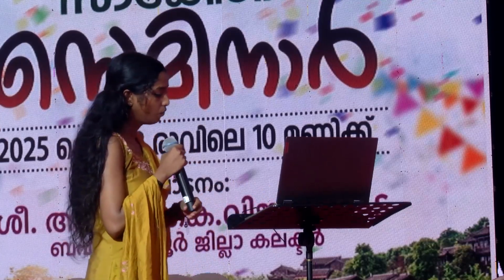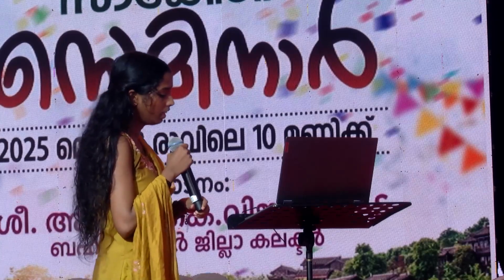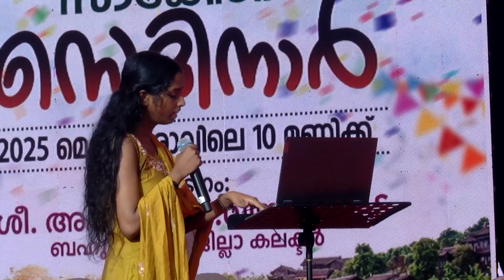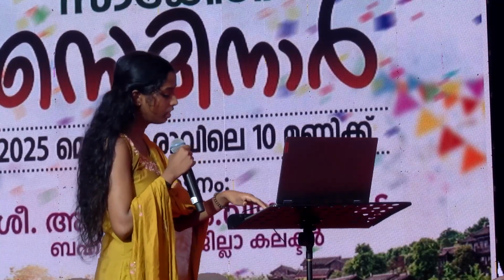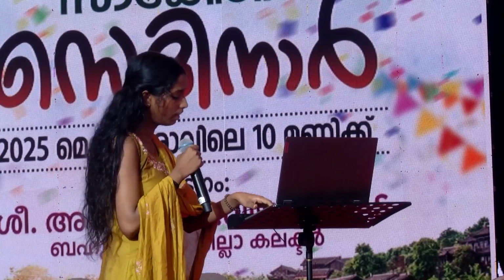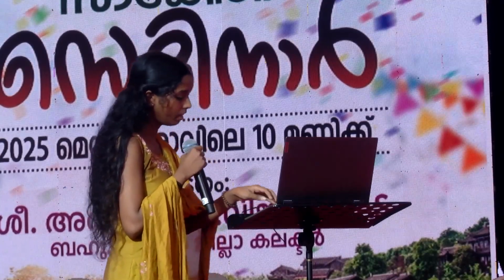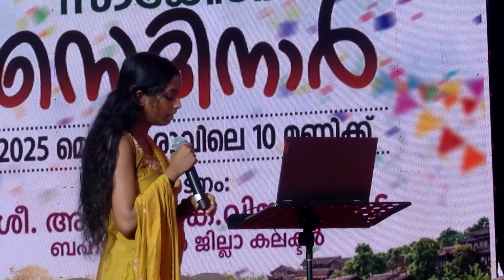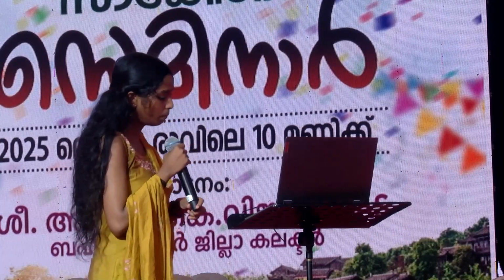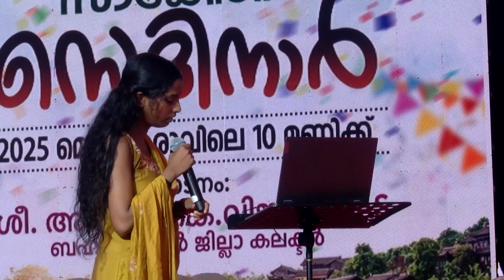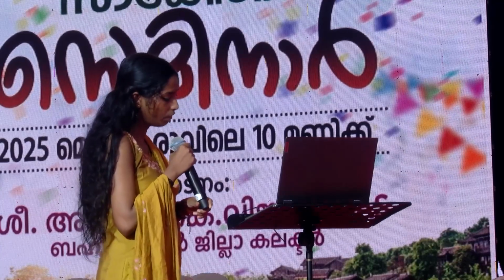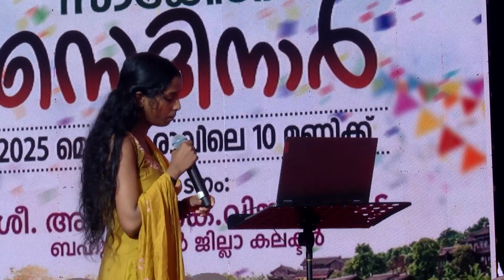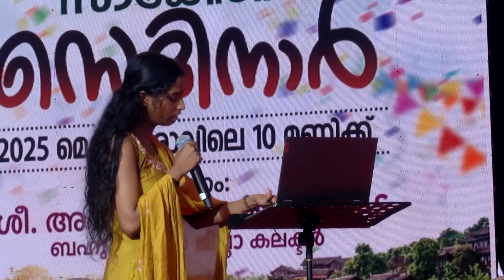The first layer is 5 centimeter thick. It has soil for plant growth. The second layer is cocoa husk, and the third layer is fine aggregate. The last layer is gravel: gravel of 40 mm effective diameter, 10 centimeter thick; gravel of 20 mm effective diameter, 5 centimeter thick; gravel of 10 mm effective diameter, 5 centimeter thick; and gravel of 4.75 mm effective diameter, 10 mm thick.